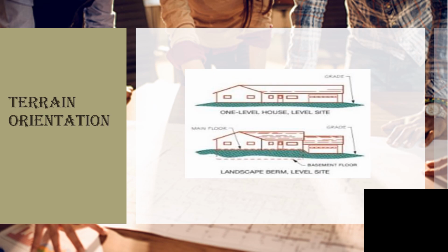For example, the excavation material plus extra topsoil could be used to construct an earth berm, which is a mound or built-up area. The advantage of the berm is to help reduce the apparent height of a second story or to add earth insulation to part of the structure.